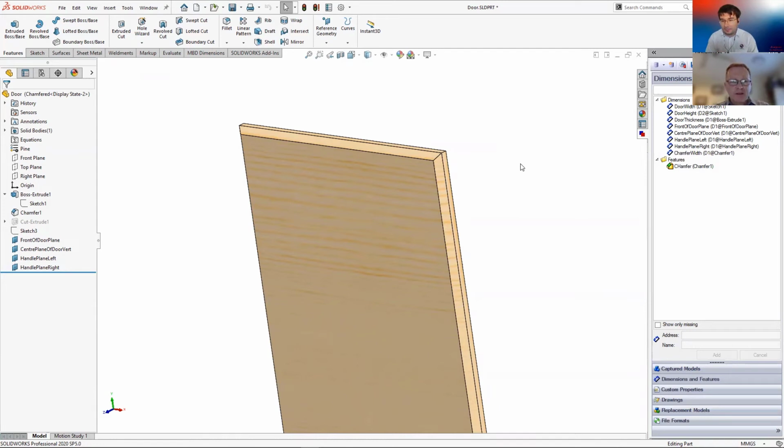Thanks for asking, Artem. That's a good thing to ask, because DriveWorks is pushing or driving SolidWorks, the philosophy behind DriveWorks is to work with bottom-up assemblies. So if you have top-down assemblies, there'll already be relations in there that DriveWorks can't work with. So you can get away with some sort of single-level top-down assembly modeling, but it's preferable to have it purely bottom-up, if at all possible. So I don't think it's a limitation. It's just a bit of a requirement. And so, worst case, if you went down the DriveWorks path, you may have to do a bit of remodeling of your master assembly.